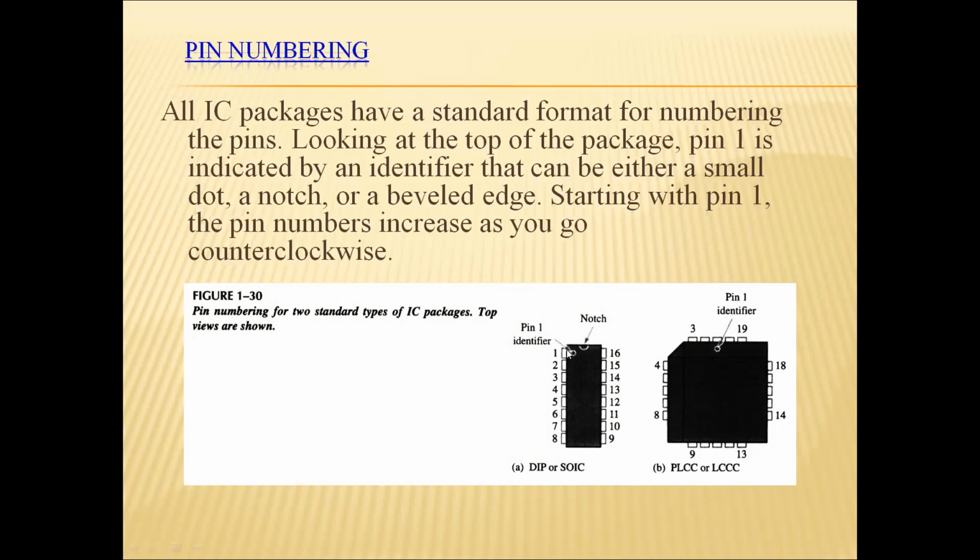The pin which is less distant is pin 1, and the one which is greater distant is the last pin. Gradually it goes from 1 to 8 and 9 to 16. This way, when you are given an IC, you should not make wrong connections, because a wrong pin selection will eventually lead you to a wrong conclusion.